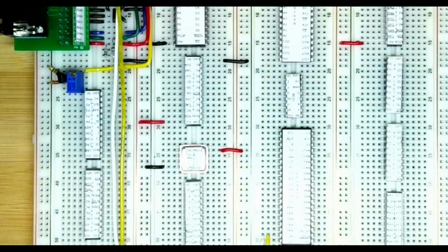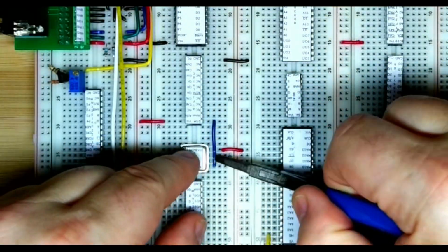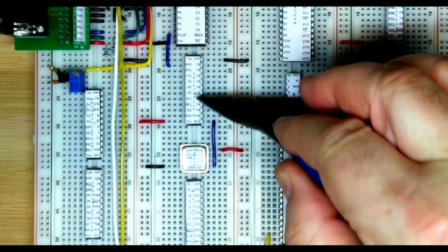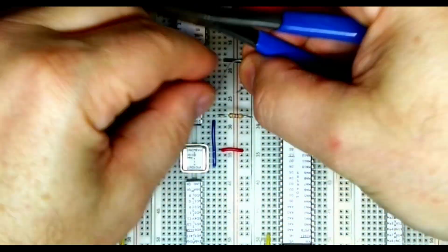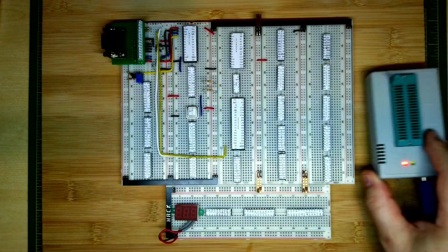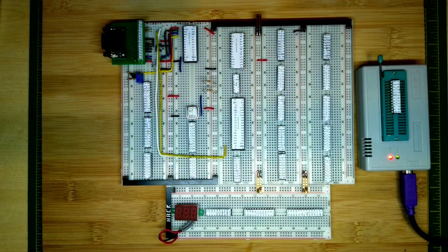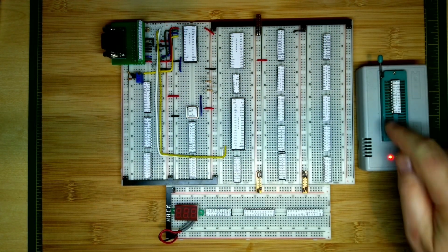So just zoom in. So you just need to wire up the clock output, 25 megahertz, then the dot clock feeding into the video DAC, and then tie those two pins to 5 volts. Okay, so now I need to program this PLD.